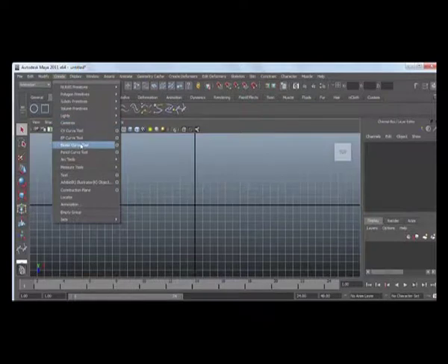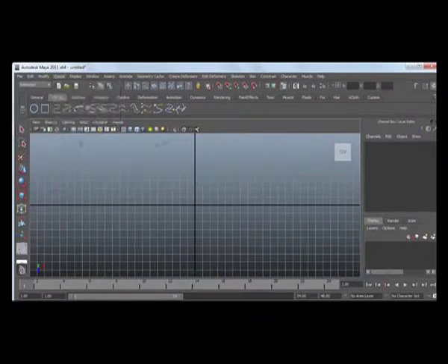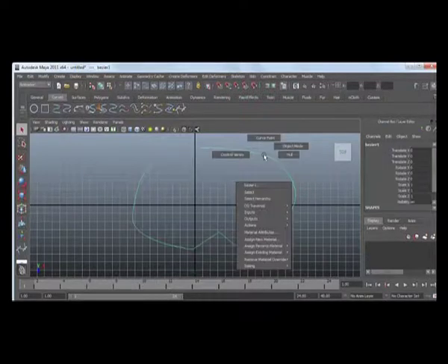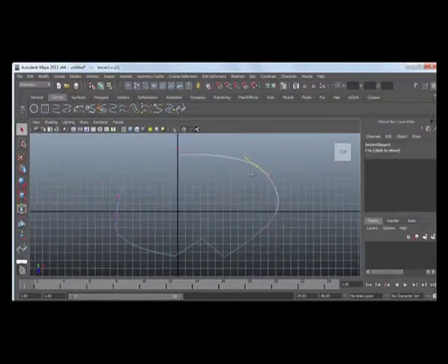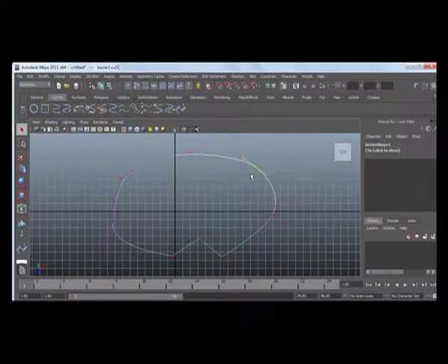The Bezier curves are a subset of NURBS curves that are composed of two types of control vertices, anchors and tangents. Anchors lie on a curve and determine the origins of the tangents. The tangents determine the shape of the curve and lead to an adjacent anchor. Since Bezier curves are a subset of NURBS curves, you can perform the majority of NURBS operations on Bezier curves as well. You can also perform NURBS operations on a combination of Bezier curves and NURBS curves. In general, an operation involving all Bezier curves results in a Bezier curve, while an operation involving a combination of Bezier and NURBS curves results in a NURBS curve.